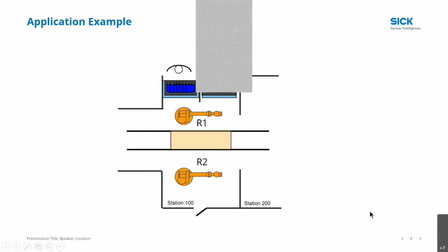So let's go through an example. This is two robots, maybe doing some processing, and then in the upper left, once that processing is complete, robot 1 will be interacting with the person who's accessing the parts on that rack. Let's say that person only interacts with that shared workspace maybe once an hour, but obviously, getting hit by the robot, the severity would be high. It could cause death or permanent injury, and it could be difficult to avoid the interaction with the robot. It could be difficult to avoid a swinging robot.